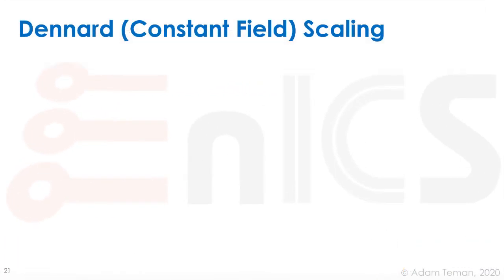So at the end of the first section, we discussed the goals of technology scaling. If we scale a technology by 30%, then we get a reduction of the size or the area of the device, of the transistor, by half, and then we can put twice as many devices on a chip, and that's how we can keep up Moore's Law.